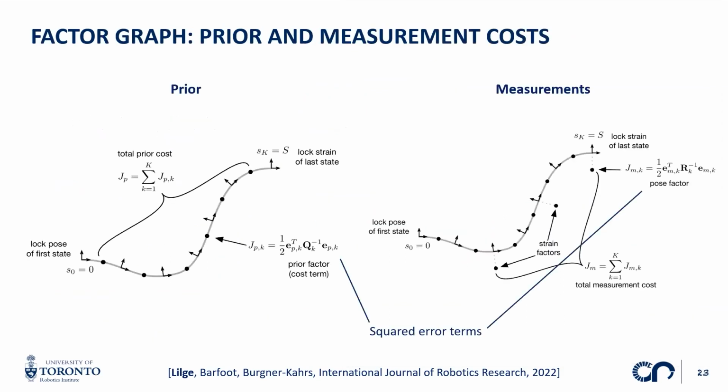Yeah, we can just directly, let's say I have a pose measurement at the last node. I just need to consider the offset to this last node. In my optimization I always have some current state of this node, right? So then I express the difference between my measurement and this node as my cost term. Now in terms of having a smooth center line, actually the prior cost will take care of that. I always have cost terms from the prior that force my rod to be smooth.